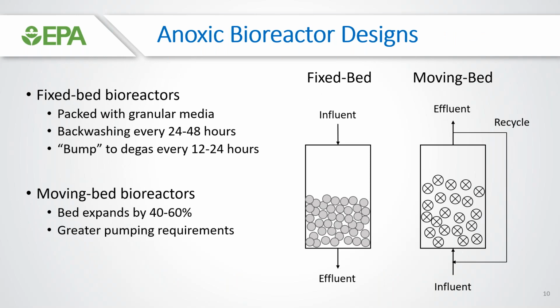There are a few different designs for this anoxic bioreactor that I want to talk about. The first is a fixed bed. So here we would have influent coming in at the top, packed with granular media like anthracite or sand, and then the effluent comes out the bottom.